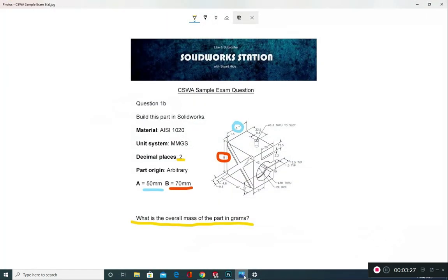Okay, I'm just going to open my drawing up and we're going to put in this circle here. This circle is diameter 38. The center of it is situated 27 millimeters from this edge, and 27 millimeters from this bottom edge. We've got a 19 mil gap here that we'll have to sort out, and then the whole thing needs to be extruded by 67. So let's go ahead and put this circle in as well, and this little bit of a gap.